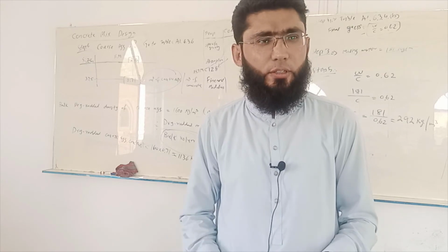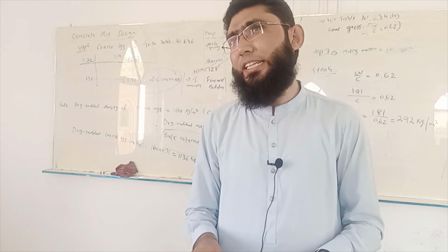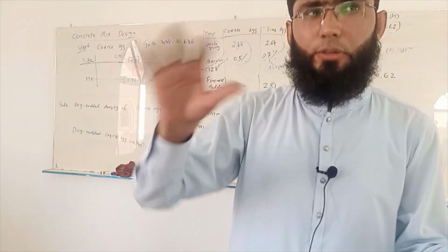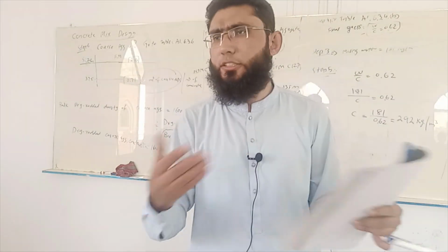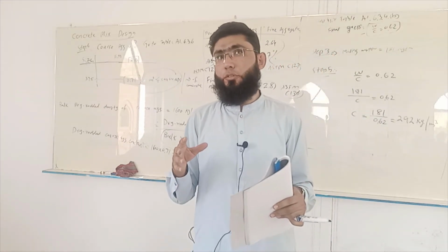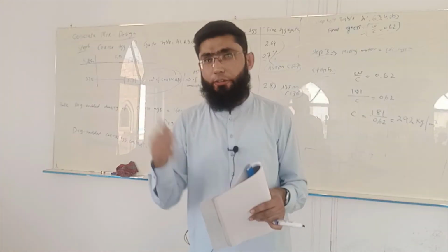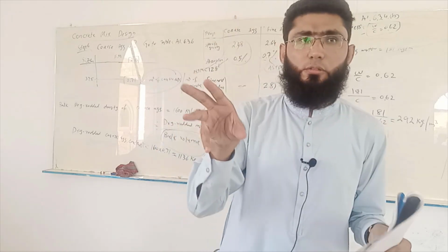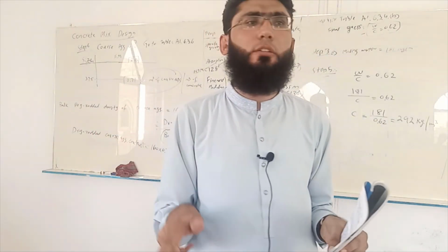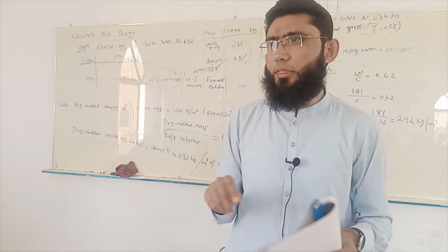Isn't it simple enough? But the problem is that it's not really easy to guess. It is possible to guess, and there are some equations to guide you. The more accurately you can guess that fresh density of concrete, the more accurate the proportioning is going to be. What is the other method?